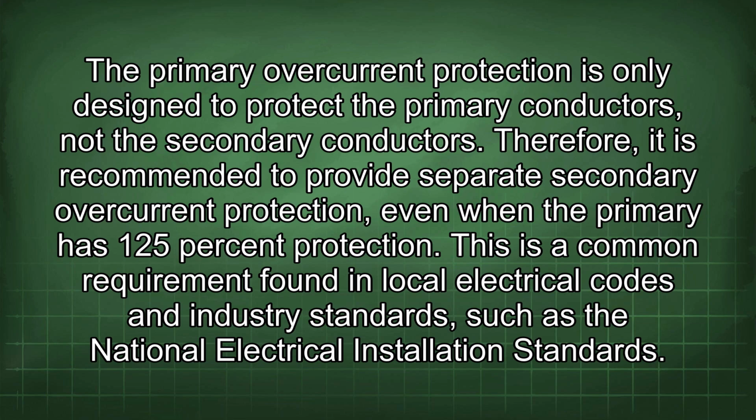Therefore, it is recommended to provide separate secondary overcurrent protection, even when the primary has 125% protection. This is a common requirement found in local electrical codes and industry standards, such as the National Electrical Installation Standards.